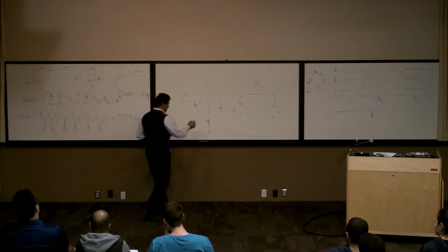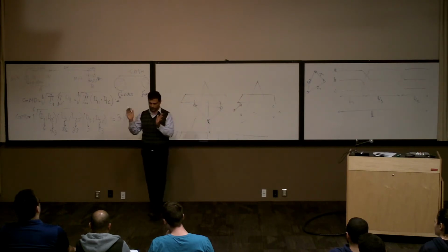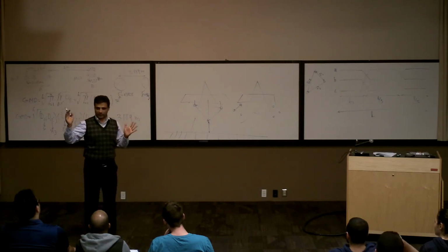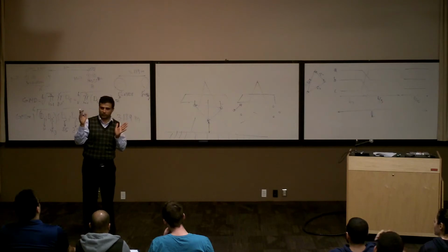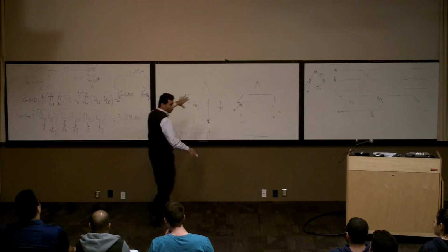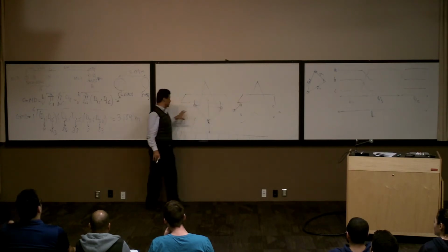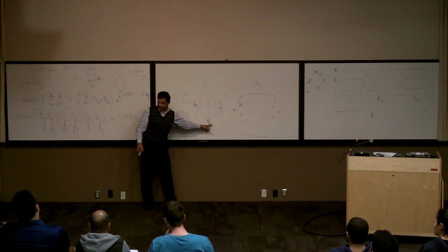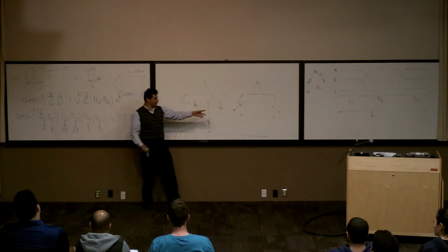So this distance also, you have to have a minimum distance, right? For example, 10 kV or 20 kV phases, you have to have a minimum distance. Otherwise, you're going to have a short circuit between the phases. When the voltage is lower, this distance is going to be smaller. When you have a million volts, you have to have a really big distance. So this one has to be as far from each other as you can.